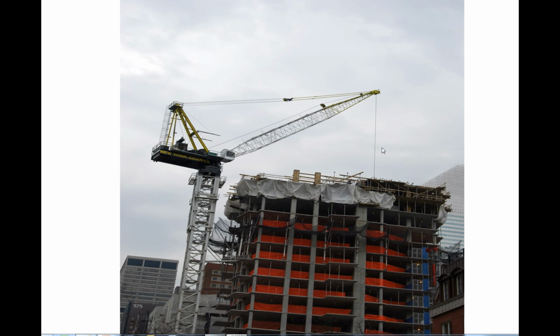It looks like it's fallen off. They need to adjust that. But as you can see from basically the first floor that you can see in the picture on up to within about 2 floors of the active construction, they have full safety netting around, and that's pretty much rule of thumb. I think you're allowed to have the top 3 floors unprotected.